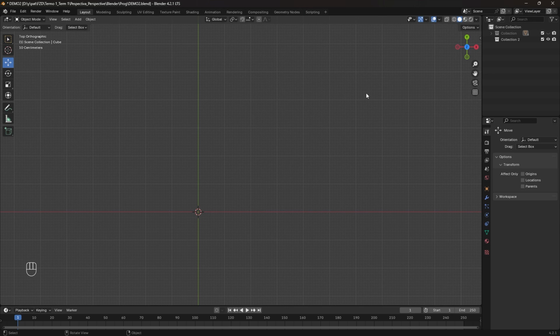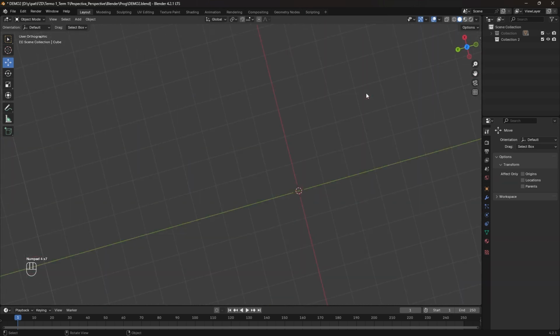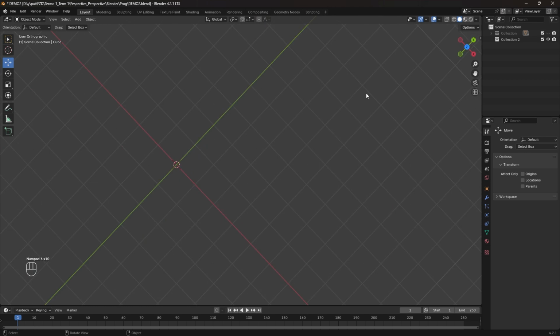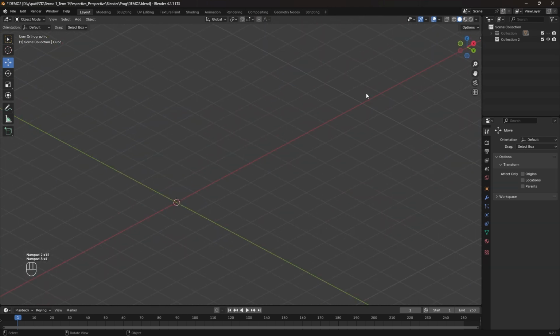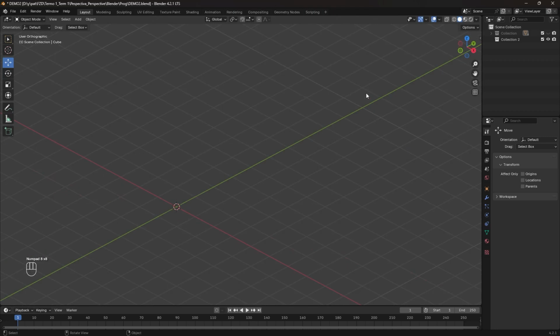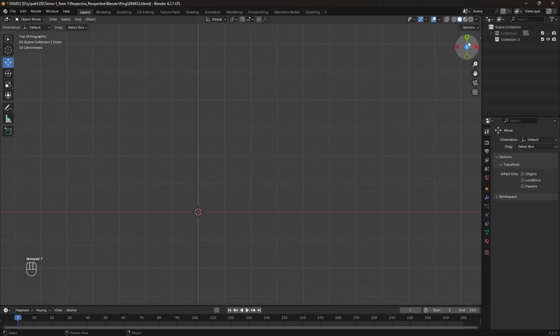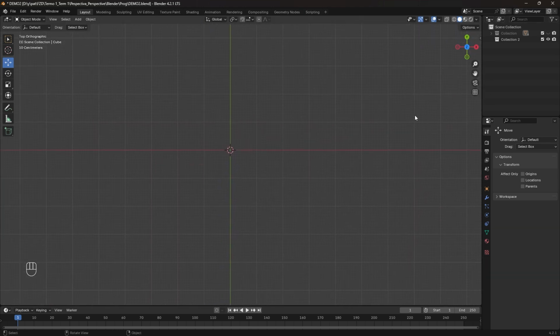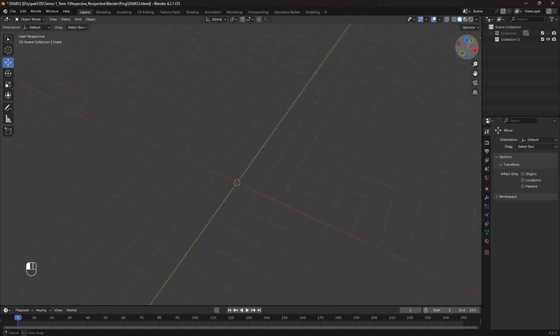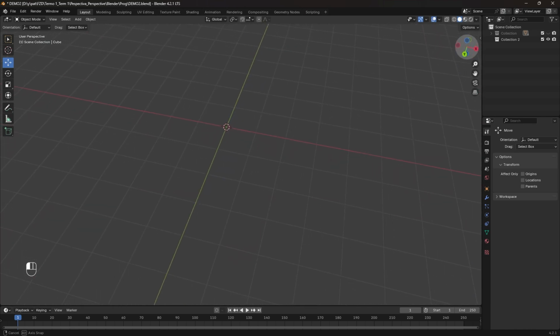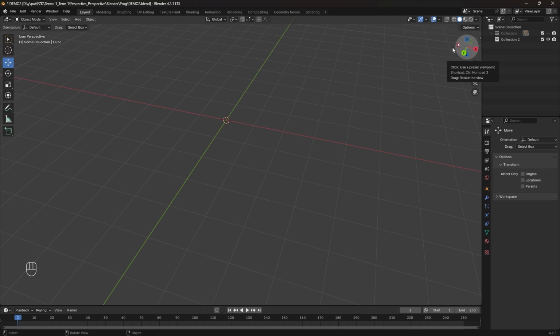And if you use 4, you will change a little bit, like you turn this. If you use 2, you will move this. Also, if you use 9, you will move this. So if we go to numpad 7, again you can do this. Numpad 9 also works. But for example, if you want to go out of this view, you can just hit 5. So 5 will make you go out of that orthographic view and go to a normal view based on the last reference.